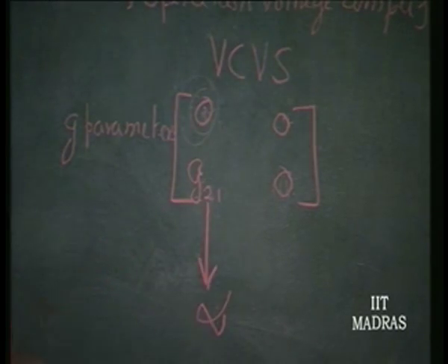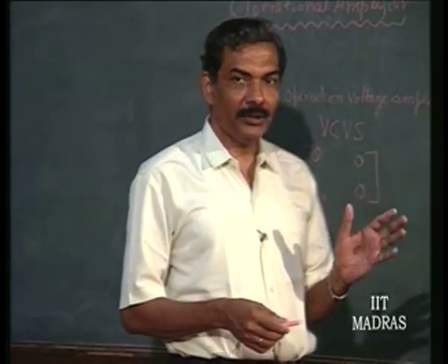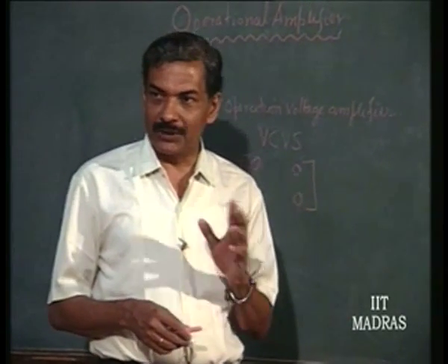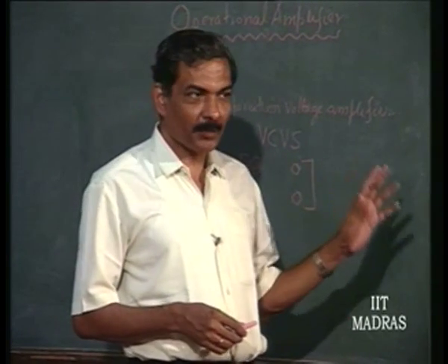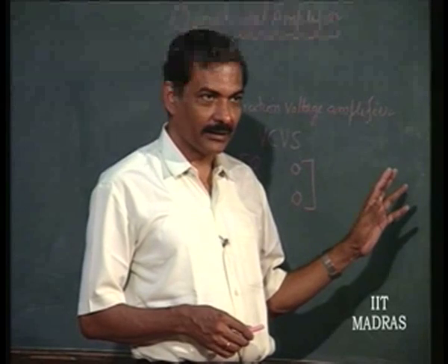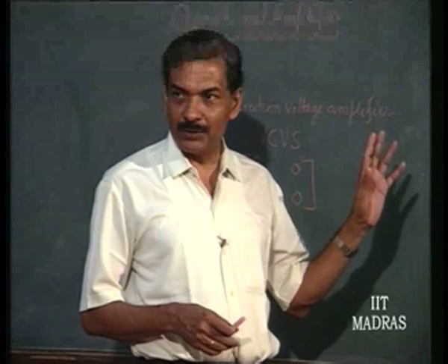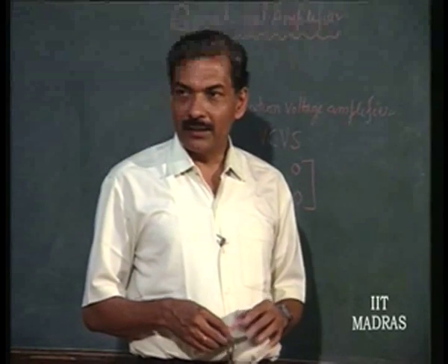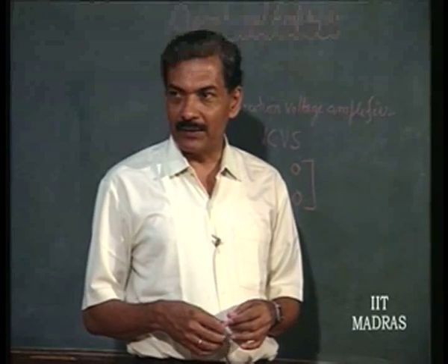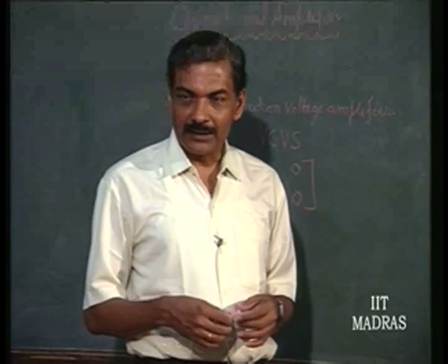Output responsibility is given to the output stage, responsibility of high input impedance is given to the input stage, then the gain responsibility is given to an intermediate stage.